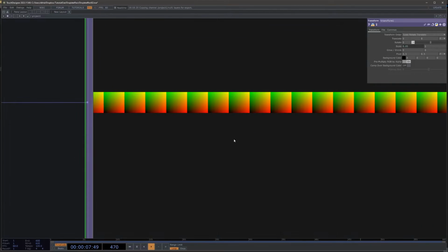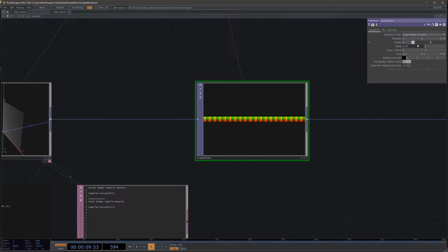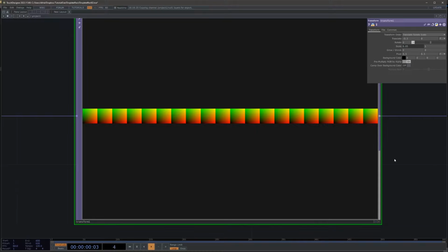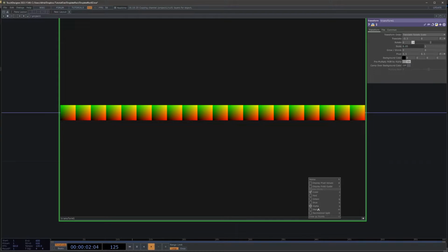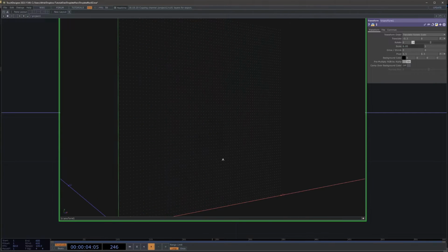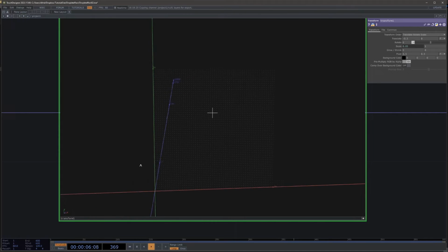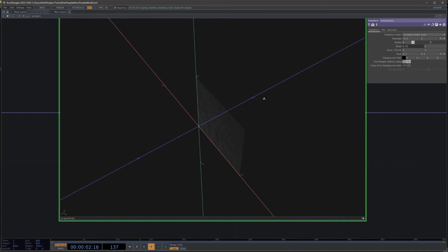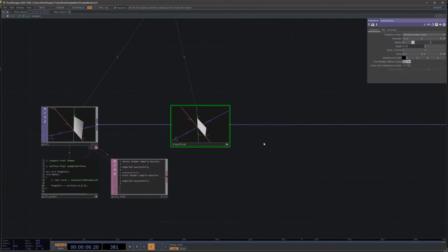So now we have 20 layers, and I'm going to set an offset of -0.5 in the translate, and in the scale order I'm going to choose the last option. So we first translate and then we scale it. And now if I activate the viewer, we still have only one grid, but each point is set 20 times. So now what I want to do is to offset it up to 1, for instance, 20 times.